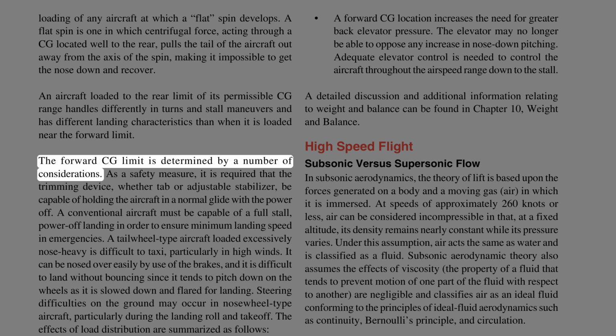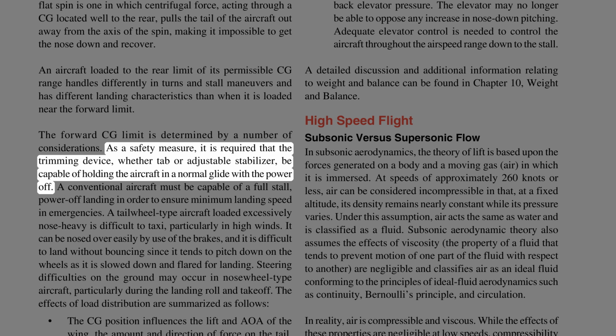The forward CG limit is determined by a number of considerations. As a safety measure, it is required that the trimming device, whether tab or adjustable stabilizer, be capable of holding the aircraft in a normal glide with the power off.